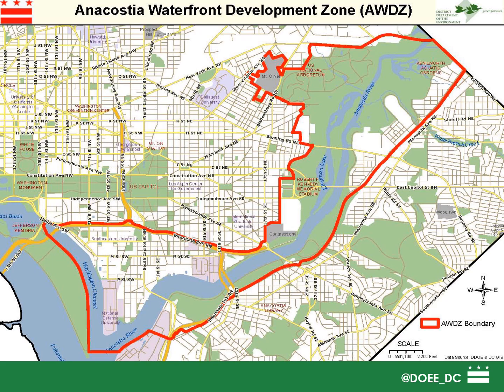There are some additional requirements that apply if you're in this Anacostia waterfront development zone, or the AWDZ, and you meet certain conditions in your projects. So if you have a project in this red outlined area here, be sure to check in Chapter 2 of the guidebook to see if the project meets the conditions for an AWDZ project, because some additional requirements will hold. Those precipitation depths that I just mentioned are slightly different in this zone, and there's an additional water quality treatment volume that must be addressed.